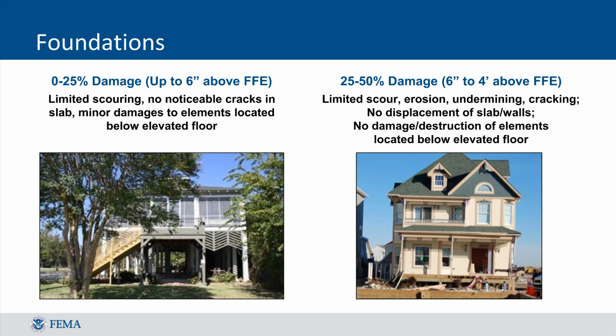Foundation damage may differ depending on the source of damage that has impacted the structure, but in all cases, you'll want to look out for erosion, scour, cracks, and undermining of the foundation. In cases where you notice only limited scour or erosion, and there are not any noticeable cracks or separation between the foundation and superstructure, you'll likely want to mark the percentage as less than 25%.